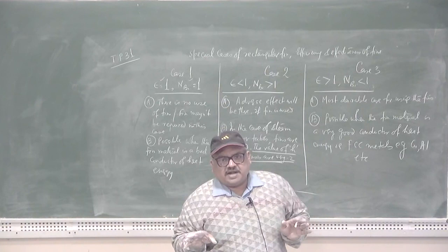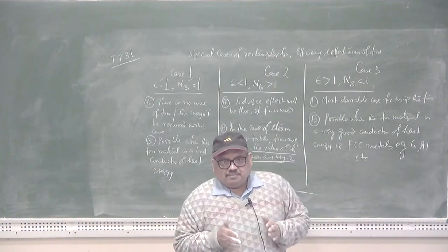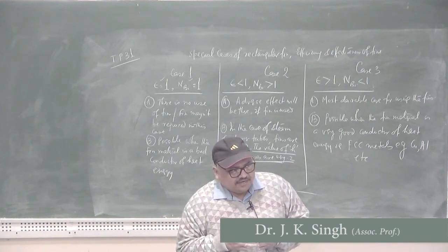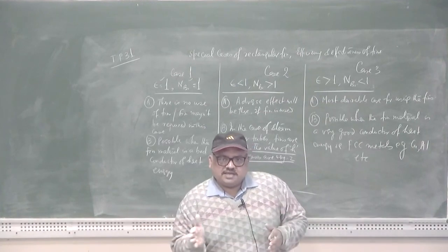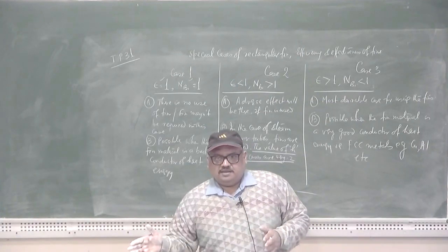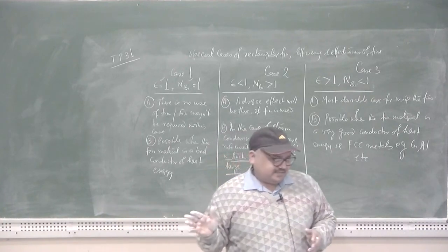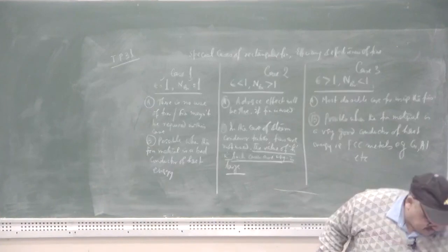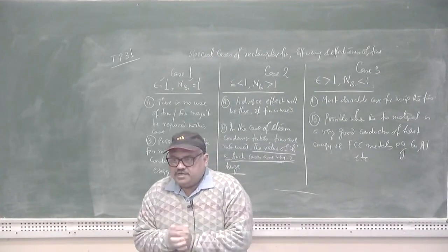In spite of the fact that the rectangular fin is 3-dimensional, we assumed that the heat flow is unidirectional, that is along the x axis, perpendicular to the cross sectional area in the heat flow direction. So, you should incorporate that assumption.